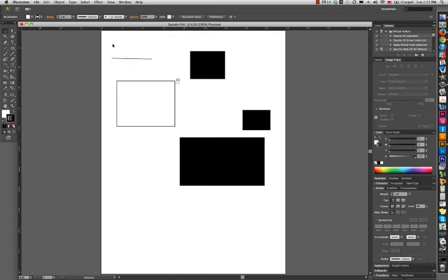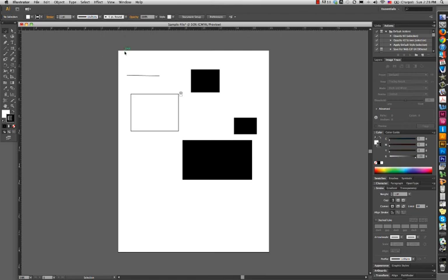But we're most often going to be working in inches. The other thing that you can do with the rulers is to set the origin. So right now you can see that the ruler is starting from the left side, going to the right side, numbering from 0 to 18 because our sheet is now 18 by 24 inches. And it's also doing the same thing from the top, let me zoom out here, from the top of the page down to the bottom, so from 0 to 24.